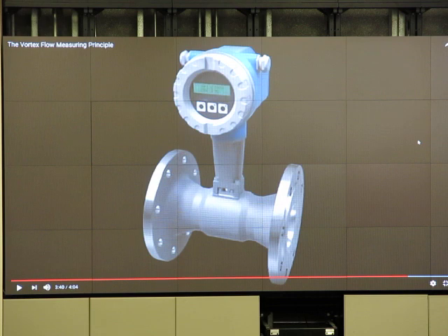No, laminar flow doesn't form vortices, only if we have turbulent flow. We need turbulent flow to create those vortices. That is why if we have laminar flow, they try to increase the velocity by reducing the cross-section area, you see? There's some modification, reduce the cross-section area and we flow faster. It said in some applications, did you watch the video? In some applications, the velocity is not high enough to create a vortex. So they reduce the cross-section area, so the velocity is going up and it becomes turbulent and then it forms vortices. And then we count the number of vortices. Good? So vortices don't form in laminar flow.